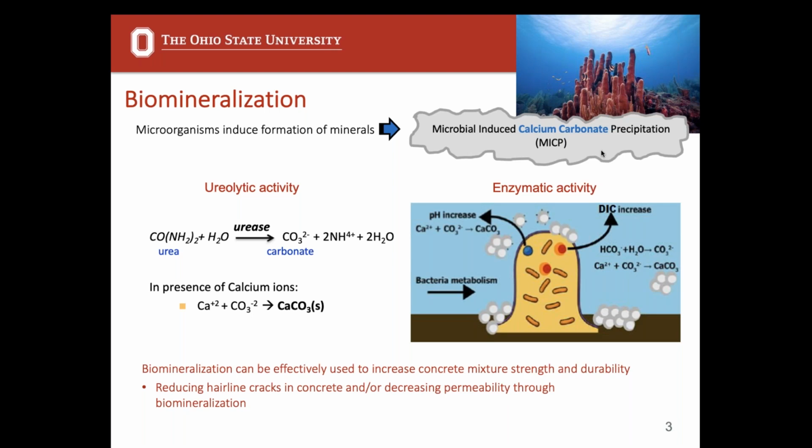So these are bacteria and other organisms that consume one product and then secrete calcium carbonate, just like limestone, to build up a structure. The idea is that we'll use these organisms to fill cracks once they happen in the concrete, or we may also be able to use them to densify the concrete, remove at least surface porosity, and reduce the amount of infiltration of things like chlorides or sulfates into our concrete matrix, thereby increasing the durability.